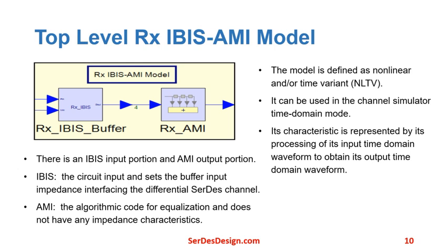Here's the top level Rx IBIS-AMI model. There's an IBIS portion and an AMI portion. The IBIS portion is for the circuit differential input and defines the buffer input impedance interfacing the differential SerDes channel. The AMI portion contains the algorithmic code that performs the equalization and does not have any impedance characteristics. The model discussed here is defined as nonlinear and/or time variant. It can be used in the channel simulator in the time domain mode. Its characteristics are represented by its processing of its input time domain waveform to obtain its output time domain waveform.